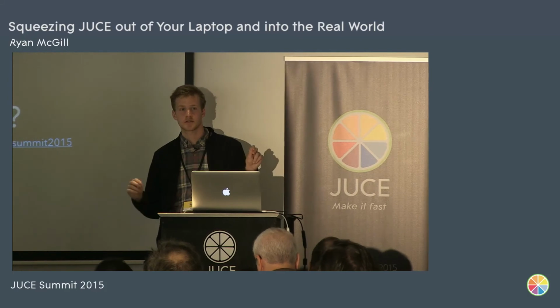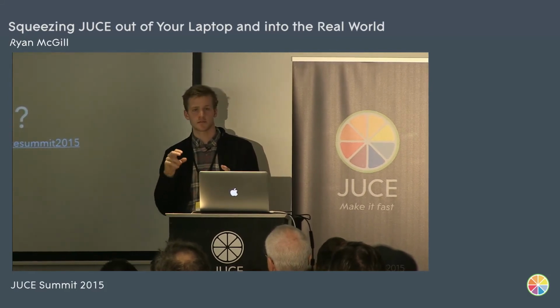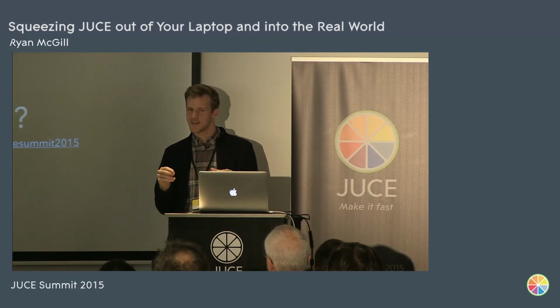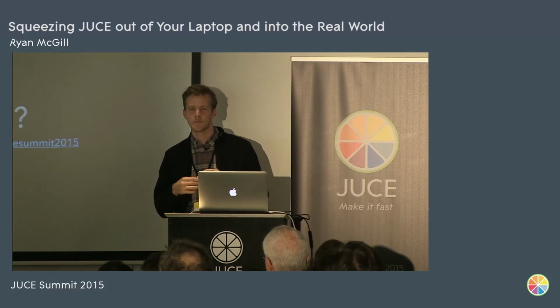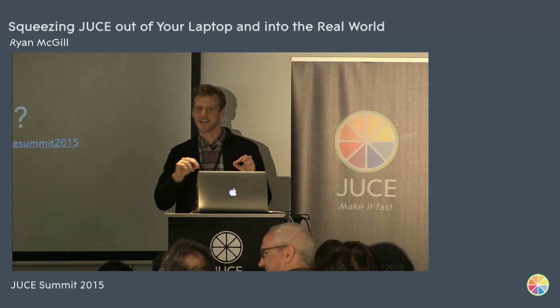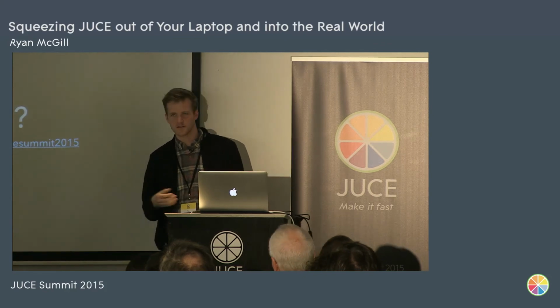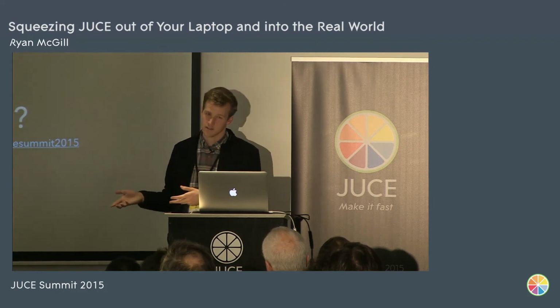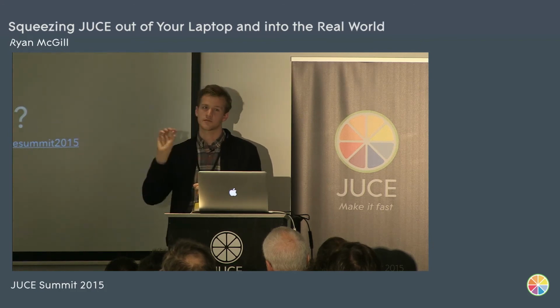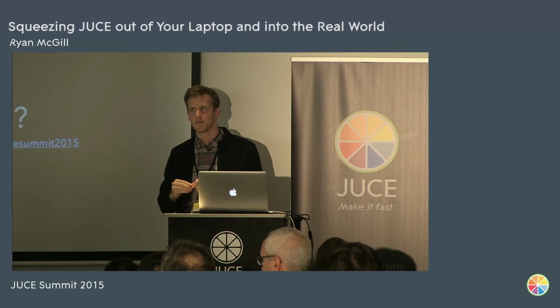But if you do need physical buttons and knobs to talk to your JUCE app, I tried a lot to use the GPIOs, which are the usual way a lot of people talk to their embedded Linux devices, and that stands for General Purpose Input Output. I didn't really like doing that as much. I think the best option would be to build a smaller MIDI controller to connect into your device, maybe with an Arduino. It sounds like too much effort, but it integrates really well with a system that has Linux running on it, because JUCE can just read that MIDI device and create event calls based on it. So I think that might be your best option.